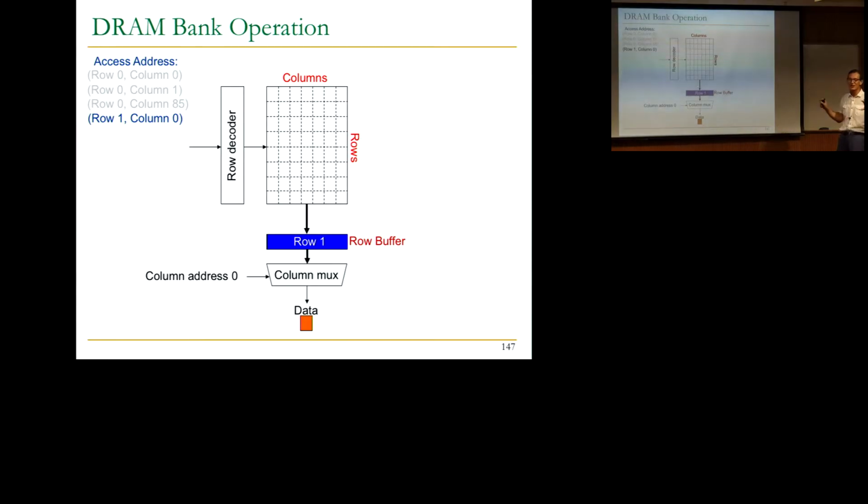It's really more like SRAM circuitry, but it has a lot of embellishments for sensing and amplification. Fundamentally, it's a cross-coupled inverter that keeps the data. You don't want to destroy the data when you access it. Here, the problem is you destroy the data when you access it. Here, you don't destroy the data when you access it. Okay?